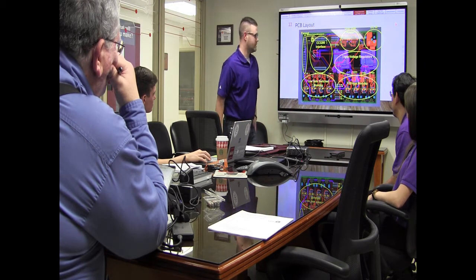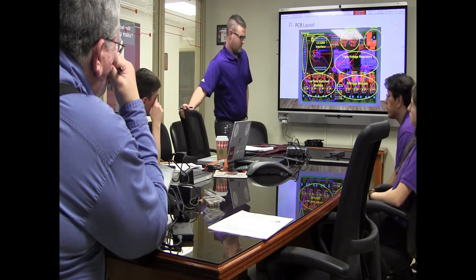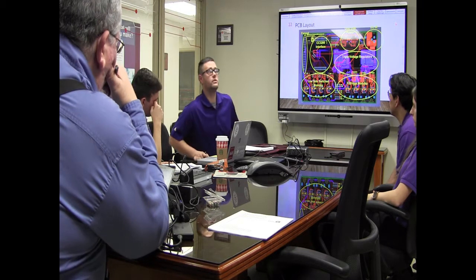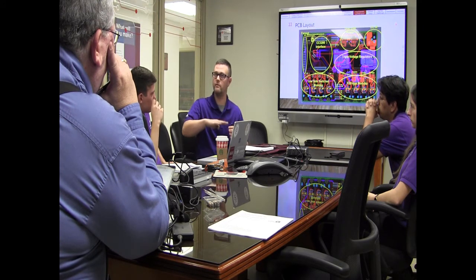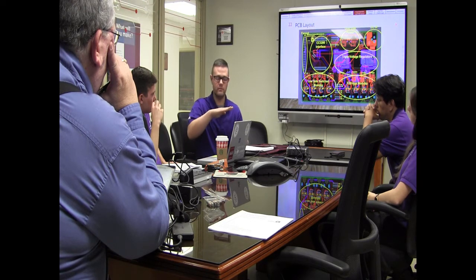Oh, yeah, there it is. And that's a right angle 40-pin connector, right? It is not a right angle. It's straight up because a lot of the connectors. Can I get to it? Yes, very easily. So the 3200 isn't covering it up? Not at all. We double checked that. And it's on the top rather than the bottom? It's on the bottom. A lot of the IDE connectors, the connector itself is right angle. So it's a crimp connection on a big flat ribbon cable, and you crimp it down, and the ribbon cable is sticking out anyways. So we thought that was pretty good.